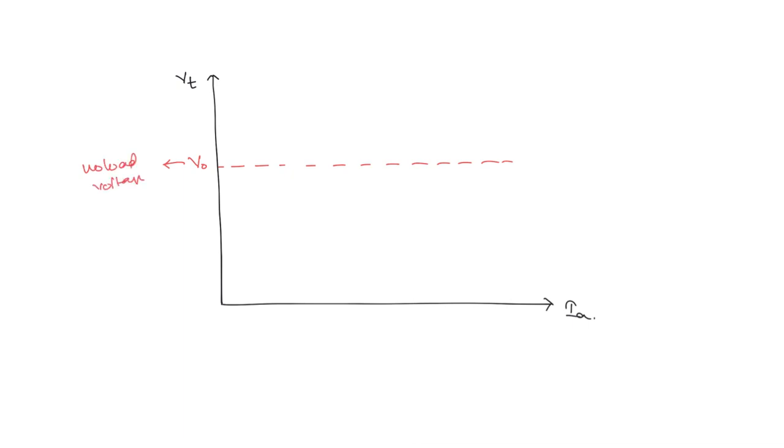Now if you draw various characteristics, okay, shunt and compound you can easily draw because we have just compared both of them. Okay. So let us say this is the under compound generator, then shunt generator is going to be something like this. Okay. What about separately excited generator? It is going to be more than the shunt generator but less than the compound generator.